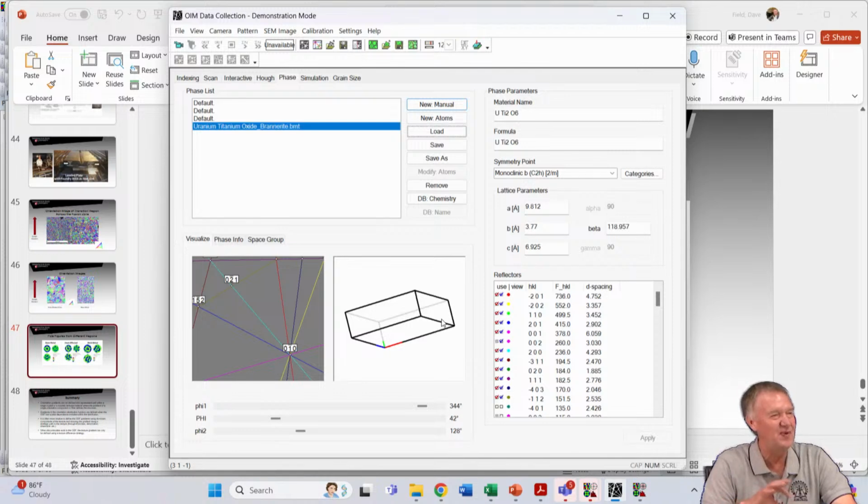So they'll tell you what the fabric is, and they'll say, we know that mountain range developed at a given temperature, and it was a shearing thrust that developed that mountain range, based on what the texture is. So just like we do with metal deformation and forensics and say this is how it formed, the geologists will go in and do the same type of analysis on the fabric or the texture of geologic specimens, and they know quite a lot about it. So there's a lot known about non-cubic and non-hexagonal structures.